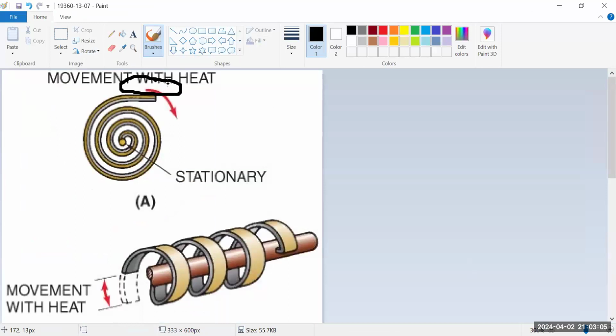And the mercury is our switch. So when it warps one way, it'll call for heating. When it warps the other way, it's going to call for cooling. So if you see a mercury bulb thermostat, mercury is a switch. Bimetal is what's sensing the room temp.